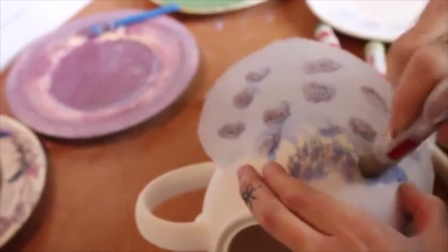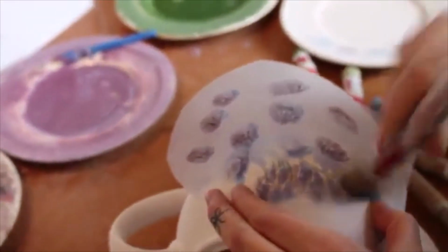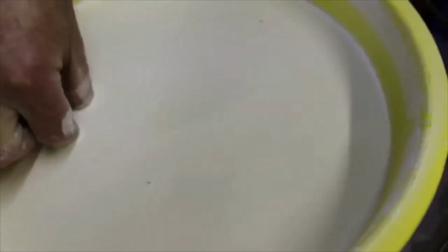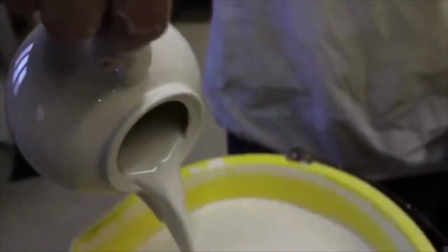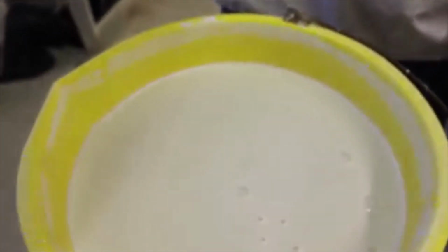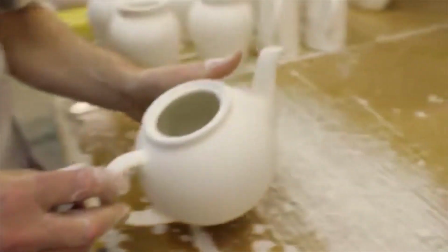Here you can see different colours are applied to 4 separate stencils to produce our Agapanthus design. Back downstairs, the items are dipped in a glaze made from sand, flint, potash and felspar, all mixed together with water. The teapot absorbs the water in the glaze, which dries quickly over the surface and coats it. The gaps left from where it is held when dipped are then covered with more glaze, applied with a paintbrush.